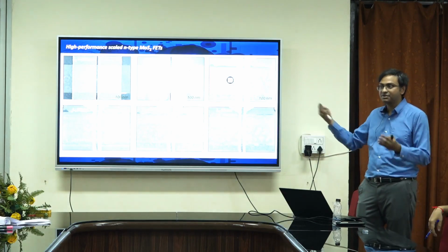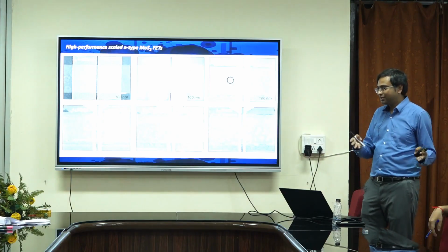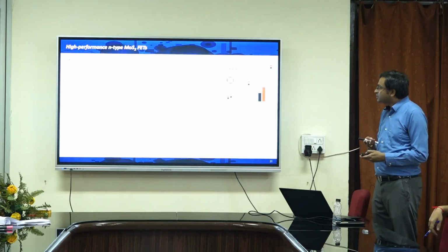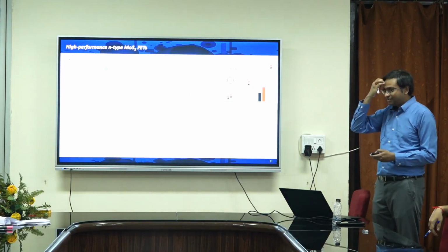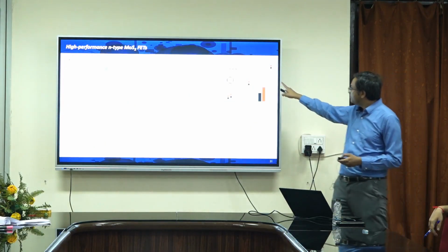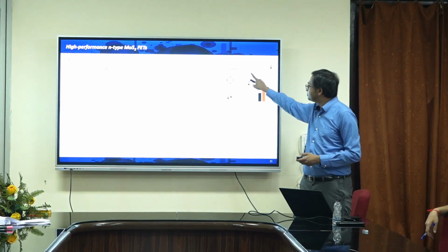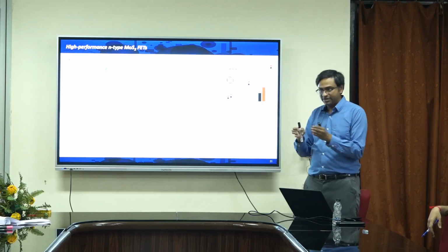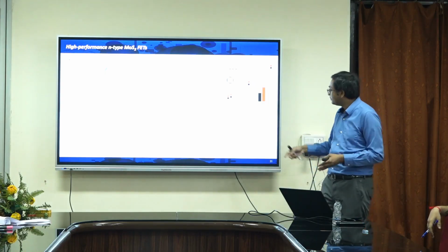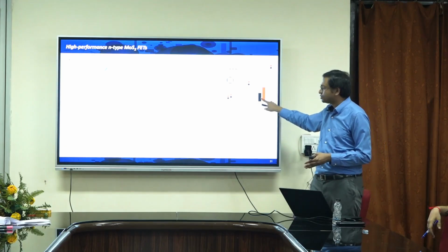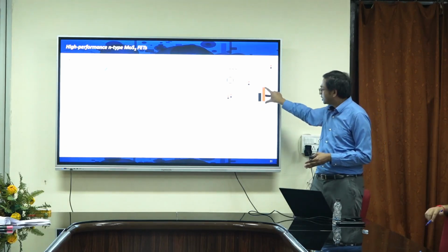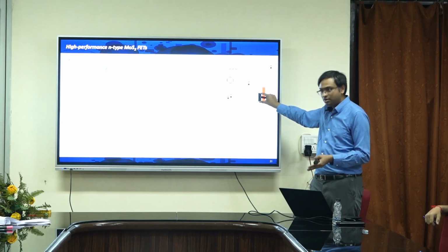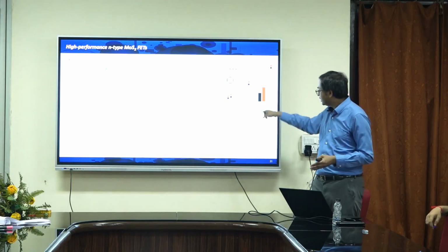So the number that we have achieved is for big contacts, and we just have seen that big contacts are not good. We found a lot of device data, don't get overwhelmed by that, but what we found is that when you make the contact very small, from 500 nanometer contact to 30 nanometer, which is what we need for our technology, you see that the contact resistance goes high. Smaller contacts have larger resistance compared to the bigger contacts.